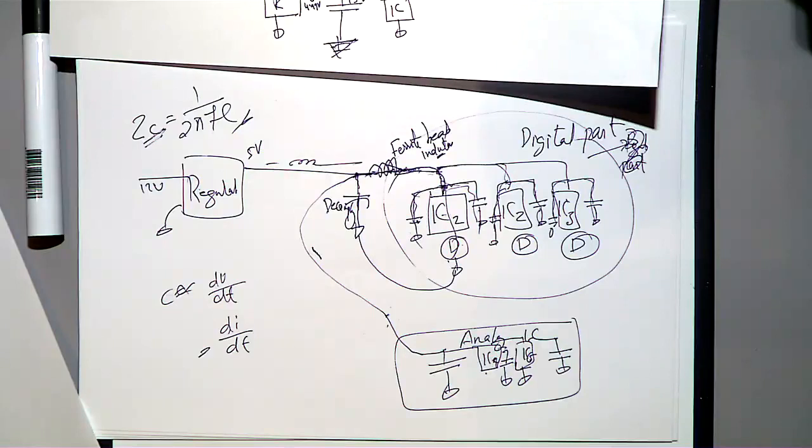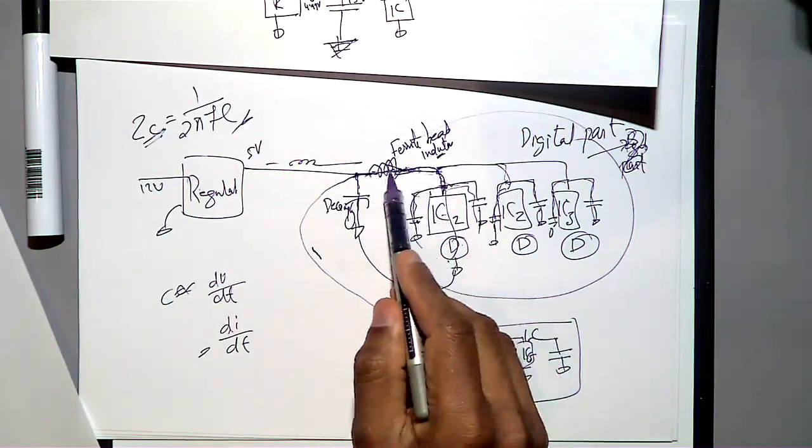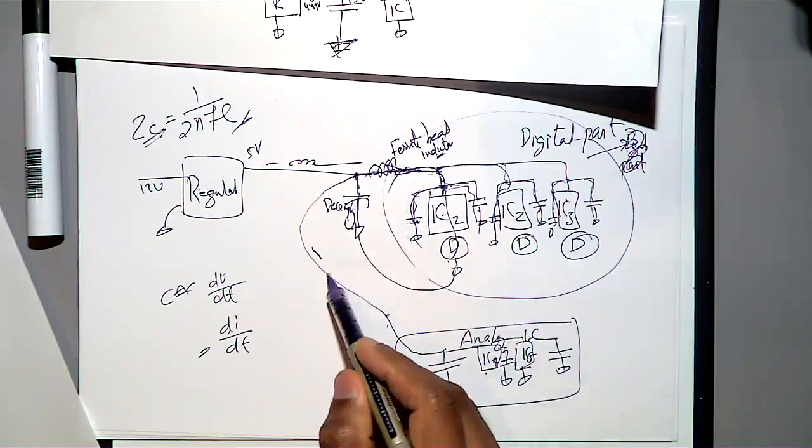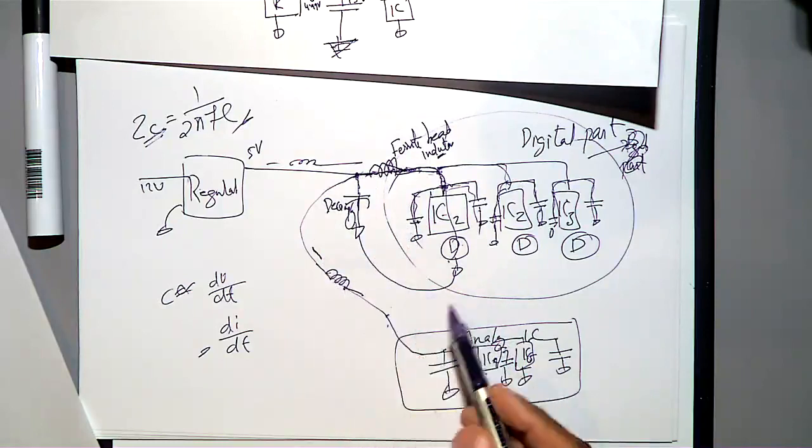So if you put a ferrite bead here, it is a very good design, so that even if the noise comes, it is not coupled to this side. If you put a ferrite bead here as well, even better. See, you got double protection, and then the analog part is completely isolated. That is the reason, when you come back to the slide, this design is a very good one. See, here you have got a voltage regulator. Now you can make sense of it.